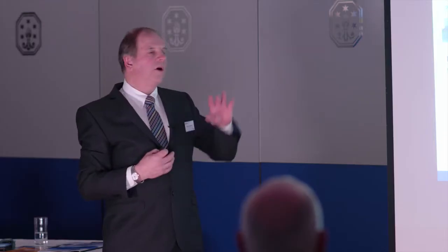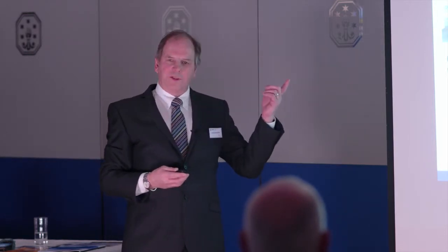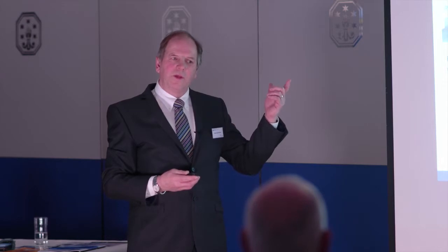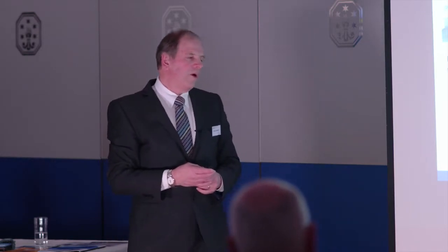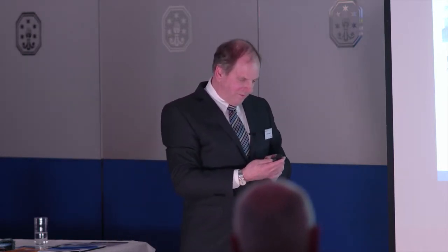There's no other support systems. The biodecon system there is all on board. The catalyst systems that are motored in and out of circuit are all on board. And this is a 1.5 hour cycle time down to 1 ppm. When we got down to 50 parts per billion, we're talking 4 hours. It just takes a little bit longer there, but primarily that's the sort of targets you can get for filling lines these days.